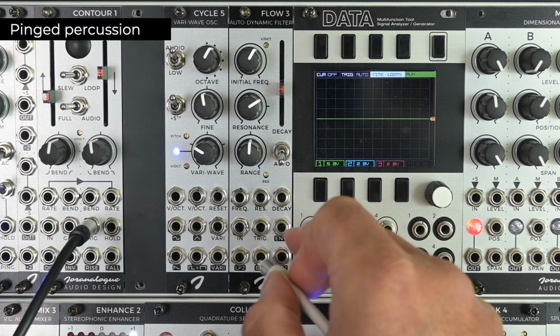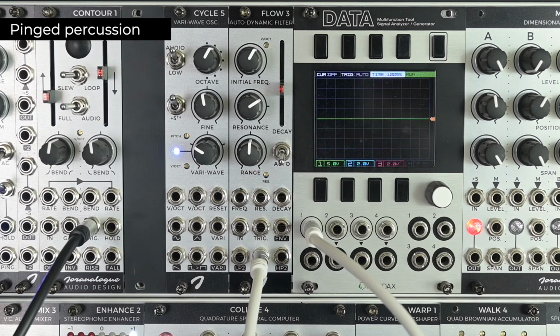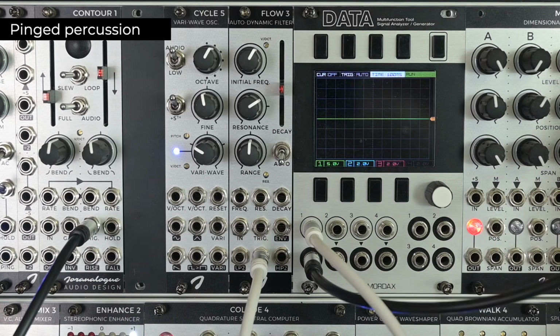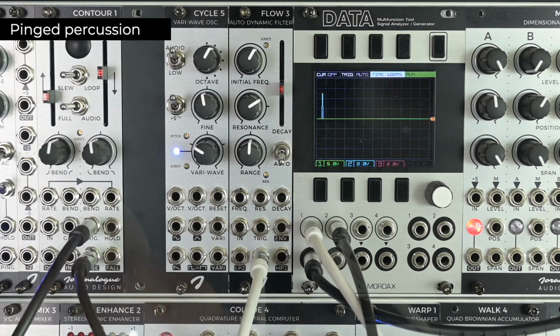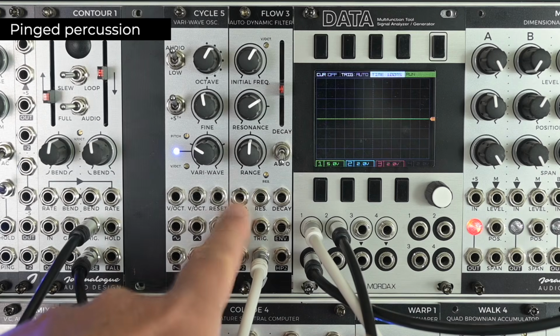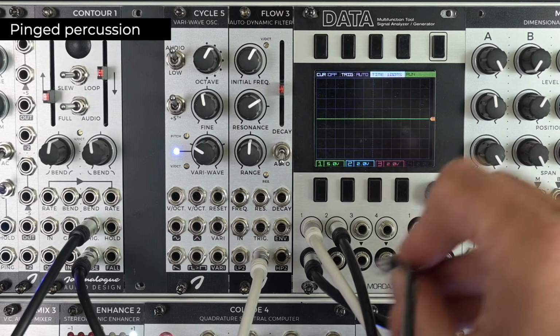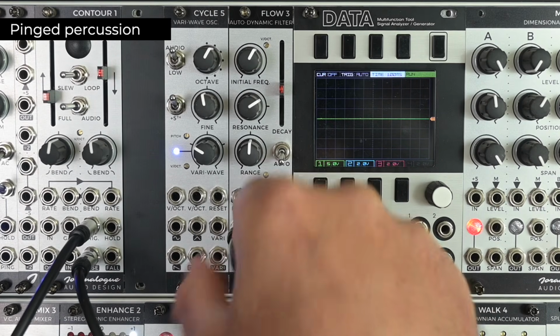And while we're talking about pinging Flow 3, let me show you how to make quick and easy drum and percussion sounds by simply sending in one trigger. So Flow 3 is still on the verge of self-oscillation. I removed the negative CV signal to the frequency modulation input, so we're just using the filter at audio rates. Let's send in a short trigger to the signal input.